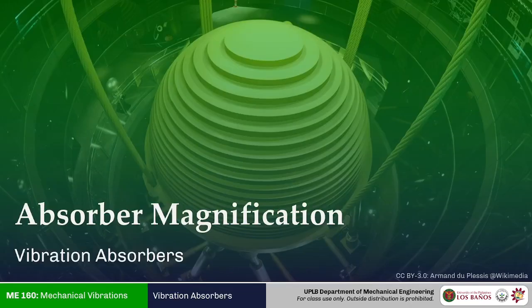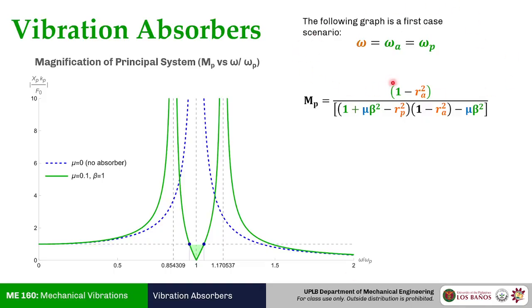All right, so let's look at the magnification now. That is our model. Let's graph it. So what we have here is our case one. We assume that the primary frequency is the one that we want to kill, the disturbing frequency. So the absorber frequency chases after omega, which just so happens to be omega P. And this is our MP expression. All right, so let's look at the graph. This is the primary magnitude and this is the primary frequency ratio. Our blue dashed line is our original primary system. And if you notice, it peaks at RP equals 1, which is resonance.